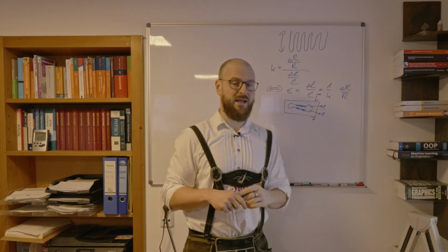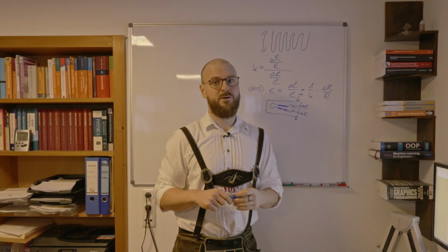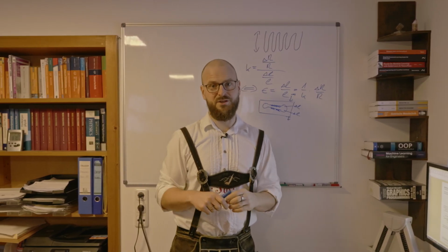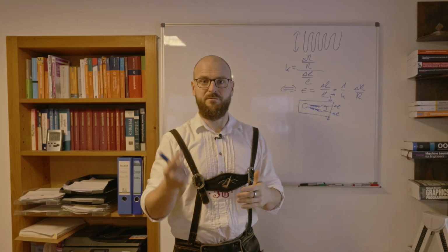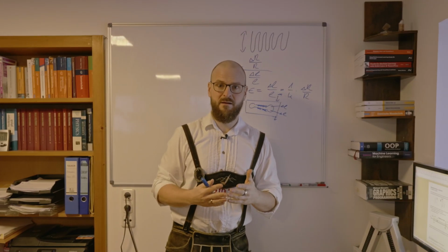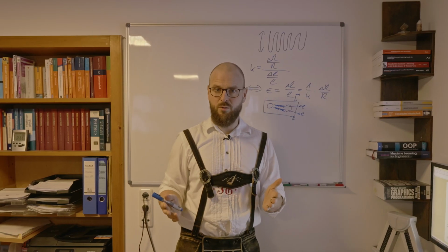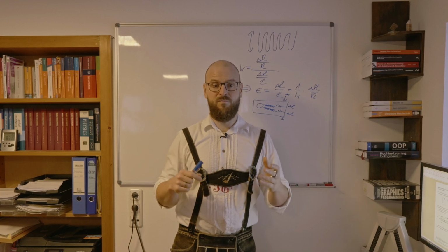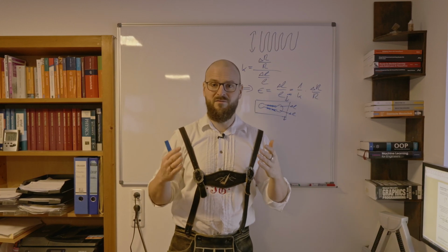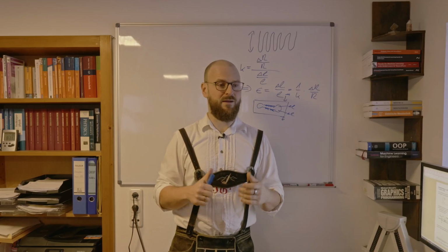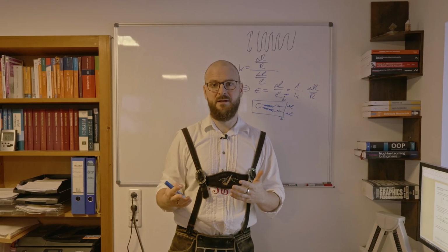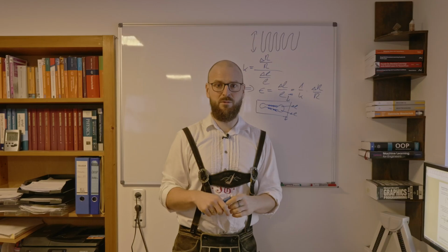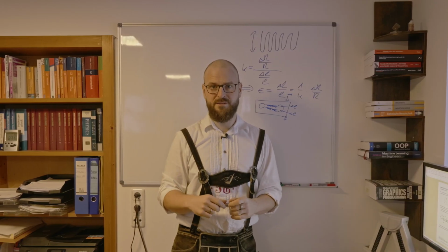A typical strain gauge would be able to deliver measurements up to the megahertz range of vibrations, for example, of a machine. For sure, those mechanical vibrations won't be that high, but for sure that means vibrations in the kilohertz range are no problem for a strain gauge. And for that reason, strain gauges are also very applicable to any vibration dynamical measurements. So overall, it's a robust, very flexible way of measuring short length scales.